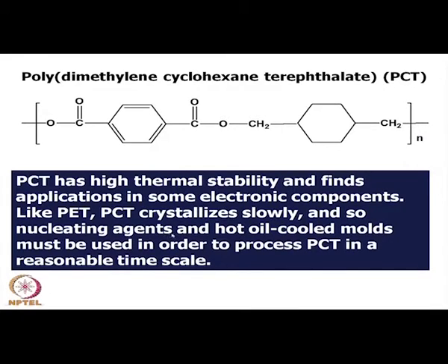If the molded item in hot condition is cooled by cold oil, that means if the mold is cooled by circulating cold oil, that can develop crystallization in the polymer. So, during processing of PCT, some nucleating agent as well as a hot oil cooled mold facility should be used to process PCT in a reasonable time scale.